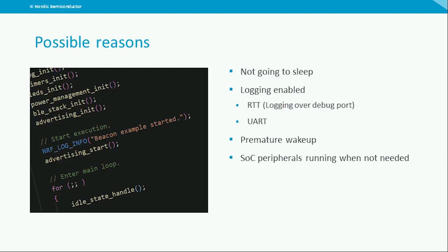Say that you are reading your sensor, getting your data and everything seems fine. But behind it all, the processor wakes up much more often than you intended, thus decreasing the battery lifetime of your product. You also have to consider how fast do you actually want to read the state of something, for instance a sensor. If you have an accelerometer and a gyro that's intended to give the user a real-time 3D representation of your product's position, then we need to have quite fast sampling. But most times we only want to know approximately the position, and maybe not that often.